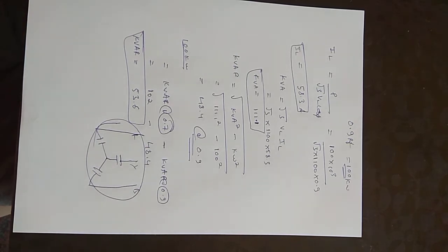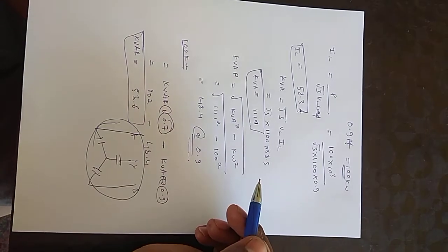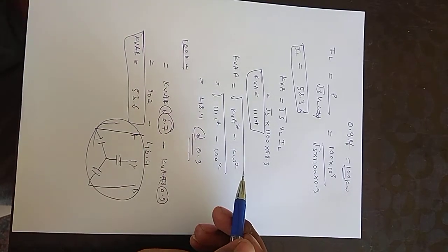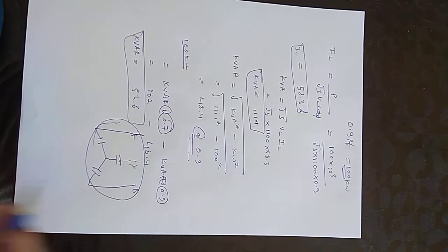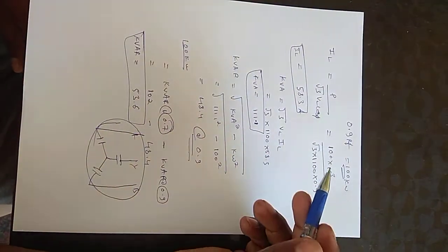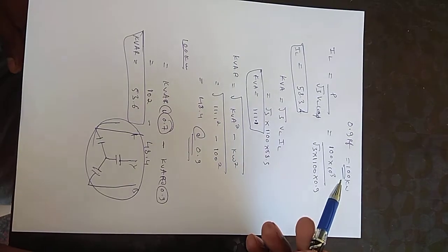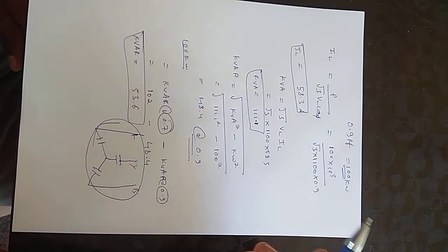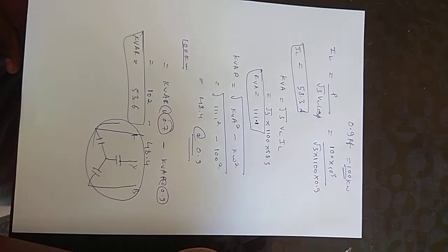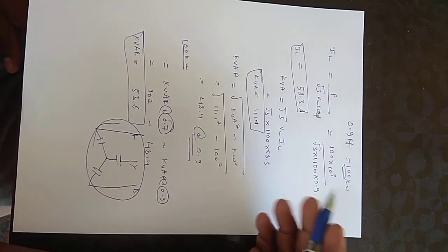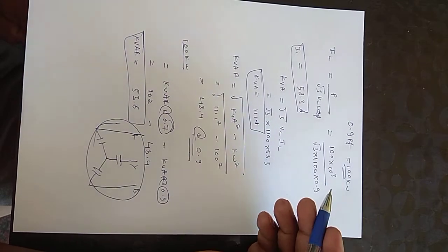Because of this, we draw less energy from the transformer, so you'll pay considerably less money compared to 0.7 power factor. This is how we increase the efficiency of the system by increasing the power factor.